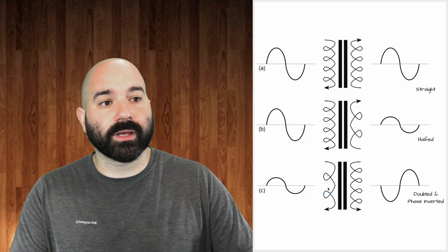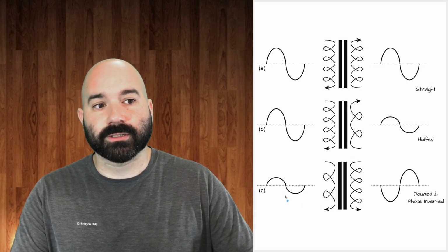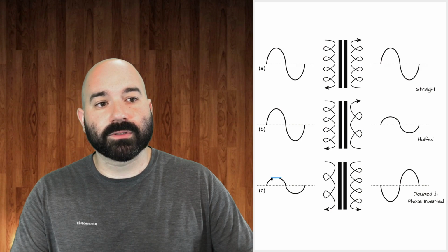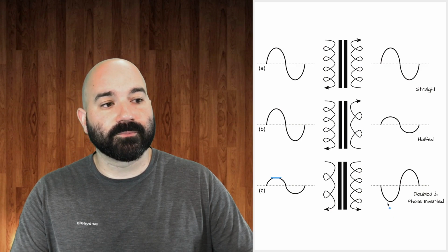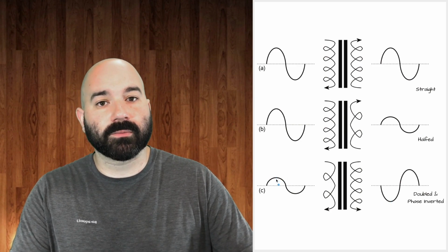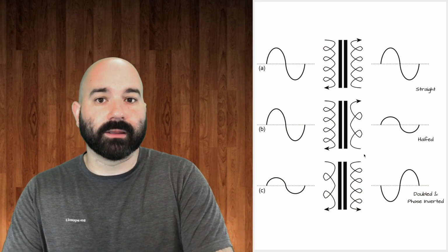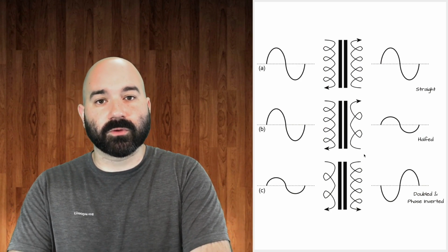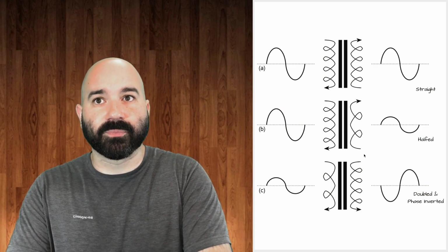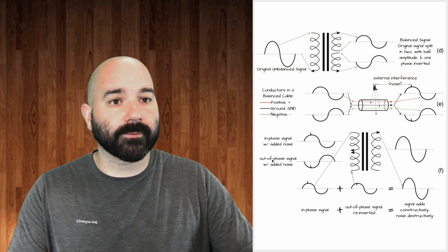In the next one, we have 2 input coils and then 4 output coils, and they are in opposite directions. So our input signal amplitude will be doubled and also be 180 degrees out of phase. Now, we already talked about phase in chapter 1, so this should not be new to you. And this transformer principle of electromagnetic induction is what creates balanced signal methods, as we'll show here on the next page in figure 18.